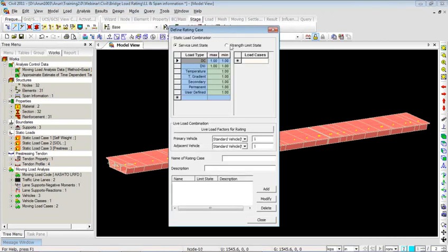So you have two limit states. I'll go first for the strength limit. I'll enter the maximum DC factor as 1.2, minimum as let's say 1, and then select the load case to which I want to consider this. So I'll select both the DC type, that is self-weight and superimposed dead loads, and then I'll come to the secondary effects, and I'll have the multiplying factor as 0.9 and selecting pre-stress load case, which is primarily for the secondary effects of the tendon.